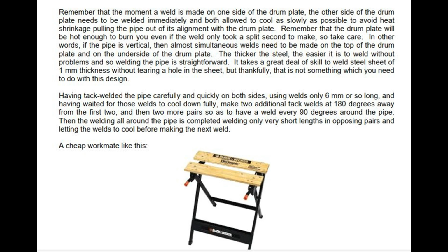Remember that the moment a weld is made on one side of the drum plate, the other side of the drum plate needs to be welded immediately and both allowed to cool as slowly as possible to avoid heat shrinkage pulling the pipe out of its alignment with the drum plate. Remember that the drum plate will be hot enough to burn you even if the weld only took a split second to make, so take care. In other words, if the pipe is vertical, then almost simultaneous welds need to be made on the top of the drum plate and on the underside of the drum plate.